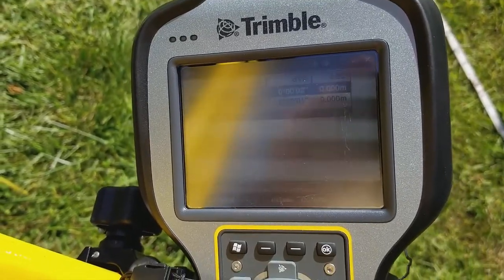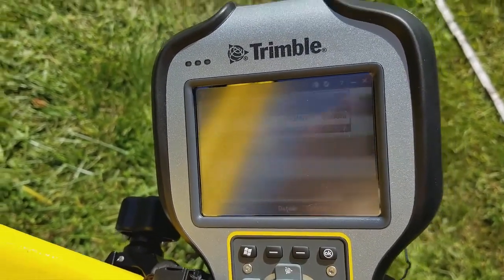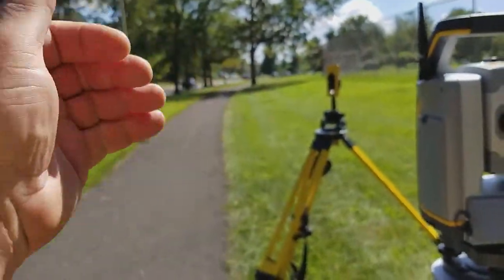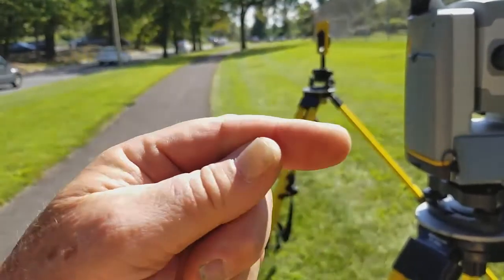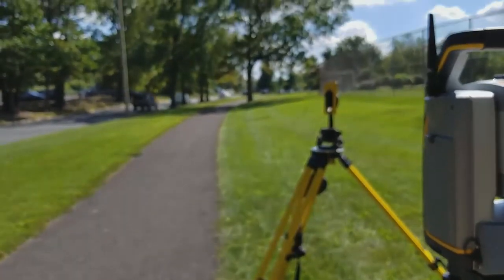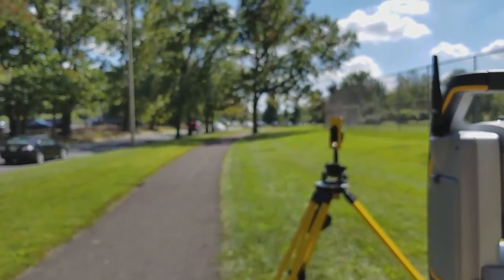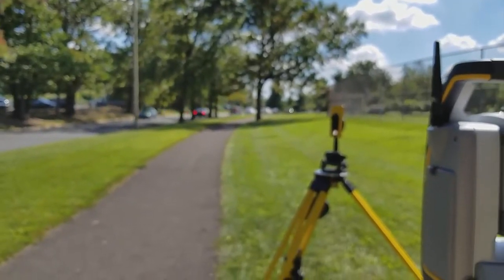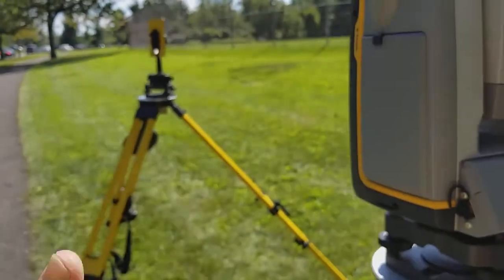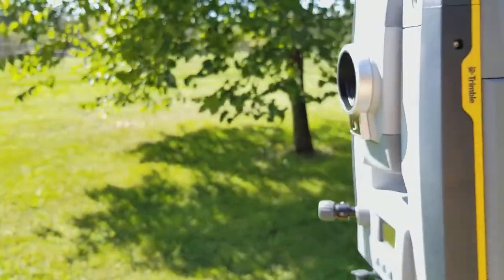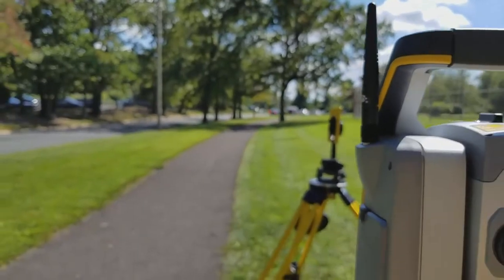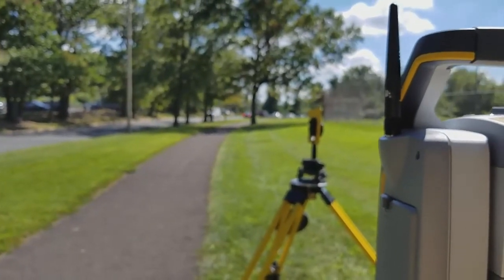All right, so I think there's one more setup. What I'll do next, I haven't done this yet, I should really sit on the geodetic monument, backsight this point, and turn an angle and measure the distance to the target that is 2 meters away. Hopefully that's not inside of the range limit on this. This thing will not measure a distance too close. I forget what it is. 2 meters might be too close. We'll find out. But anyway, we'll give it a shot.